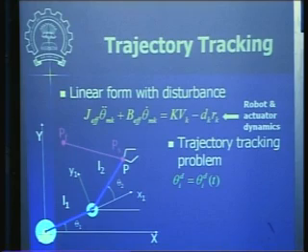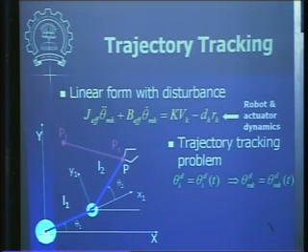Now these desired joint angles you want to convert into desired motor angles. This is the way you will find the desired motor angles, by using the gear reduction ratio; you know that there is a gear reduction from theta 1 to theta m1.